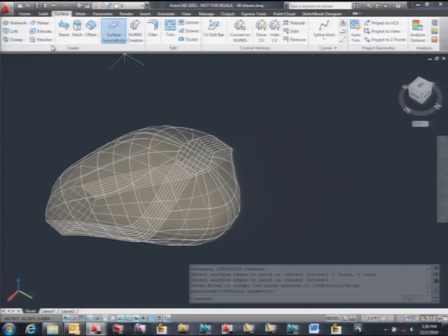It's kind of a macro. When you go into extrusion, it will say, okay, where am I? So solid tab, mode, solid, and it will do it, right? So those are commands we call ambiguous because they could be doing two different things depending where you are, right? And basically that happens to extrusions, revolutions, sweeps, and probably lofts, right? If they are coming from a closed profile and planar profile.